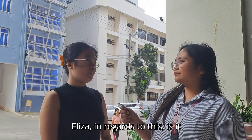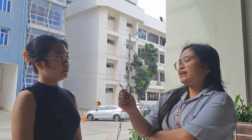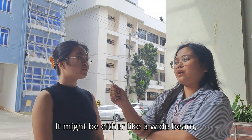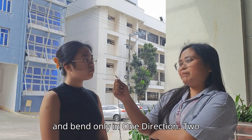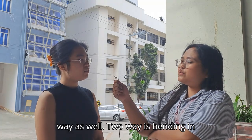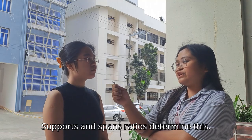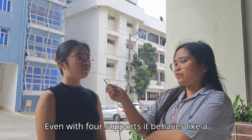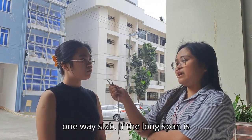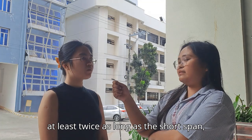Eliza, in regards to this, is it a two-way or one-way slab? It might be either. Like a wide beam, a one-way slab has support on two sides and bends only in one direction. Two-way as well? Two-way is bending in both ways and on all four sides. Supports and span ratios determine this. Even with four supports, it behaves like a one-way slab if the long span is at least twice as long as the short span.